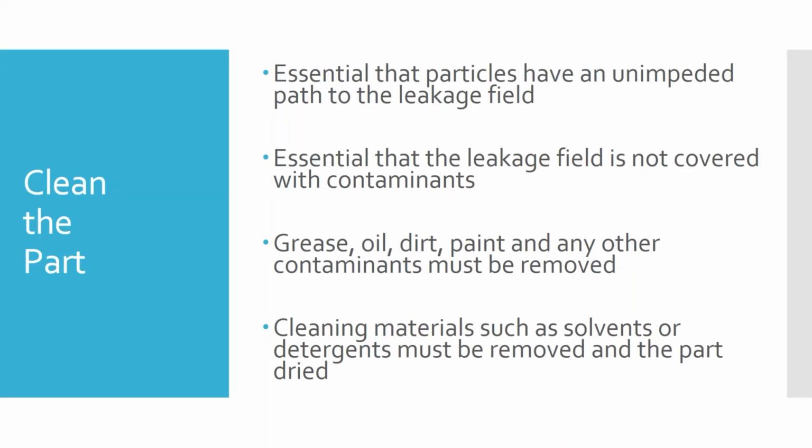So it's also essential it's not covered with contaminants. Even things like oil and grease can be thick enough that the field can't jump. Or imagine if a part's covered in a bunch of grease and you dump iron filings on it. What's going to happen? They're going to stick. Yeah, they'll get stuck everywhere. They'll get stuck in the grease or the dirt. So those all have to be removed.